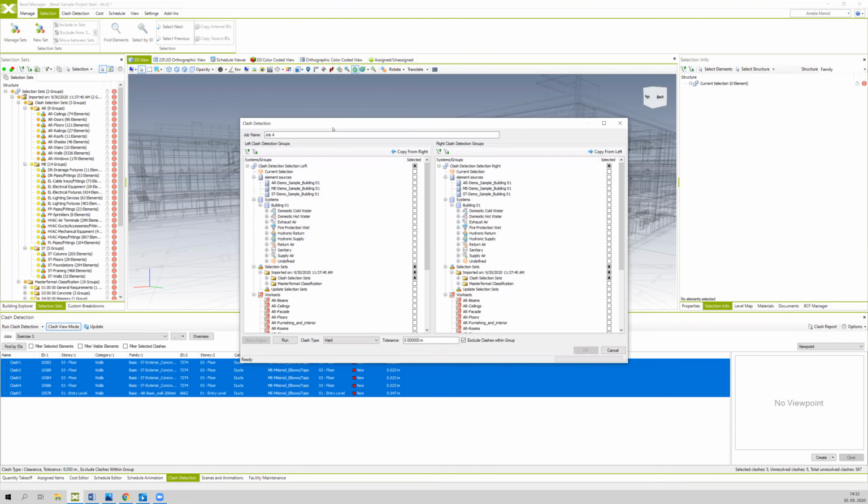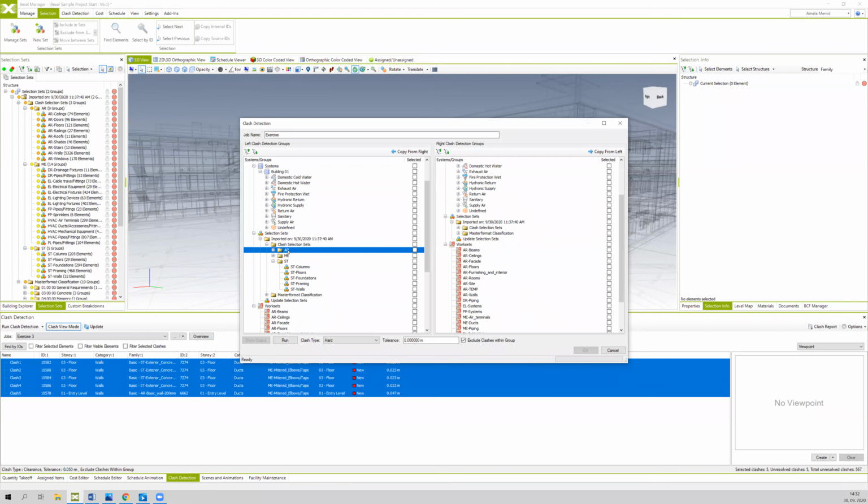And as you know, the clash detection window appears, and define the name, which is Exercise 4. Uncheck all elements previously selected, and we will look for duplicates within the architectural folder. So click on the folder AR.